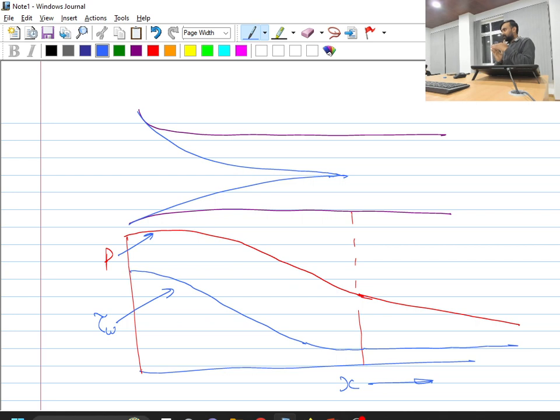viscosity has suddenly started growing the boundary layer, in the initial portion the boundary layer thickness is small. If the boundary layer thickness is small, the gradient of the velocity field will be more. Because of the high gradient of the velocity field in the entrance region, I will have a very high value of the wall shear stress as well as the pressure. So because of that, my interest is to have a smaller entrance region.